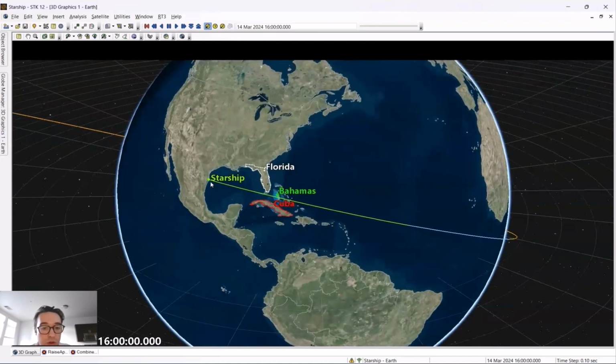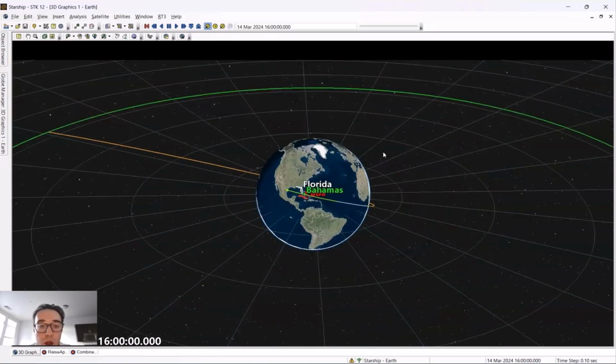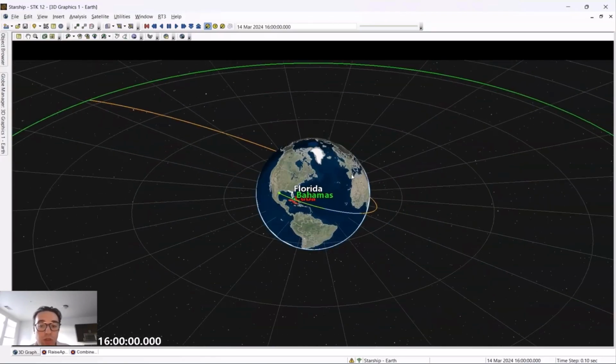First of all, because it defines your launch angle here, the initial launch angle. So it defines how you can avoid having access with your airspaces. And it also has a huge impact on your delta V compared to the downrange distance, for example, because this azimuth at burnout determines also your initial orbit inclination. And if you have a higher inclination at your initial orbit and you're actually trying to get into an equatorial orbit with an inclination equal to 0, then you're going to burn more fuel.